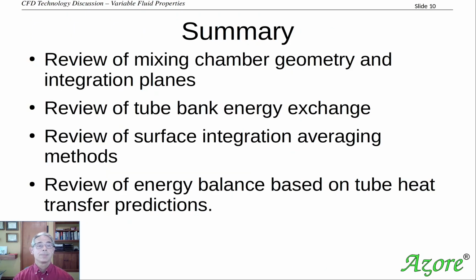So in summary, we've reviewed a mixing chamber and the geometry. This is, of course, the third case that we've looked at for this particular geometry. We've reviewed how the tube bank energy exchange happens and how we changed it. We've again reviewed surface integration methods, and then we've looked at the energy balance in these curves to look at how the temperature changes as the energy is removed and added into our system.